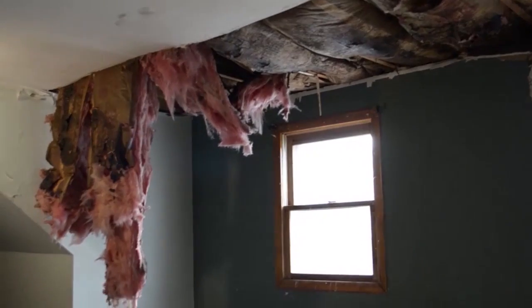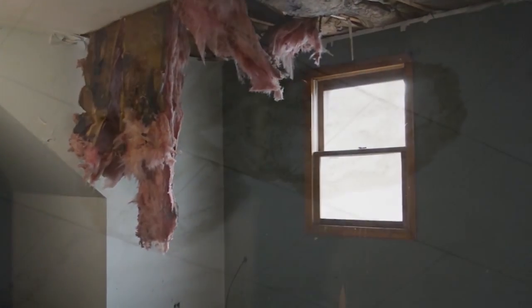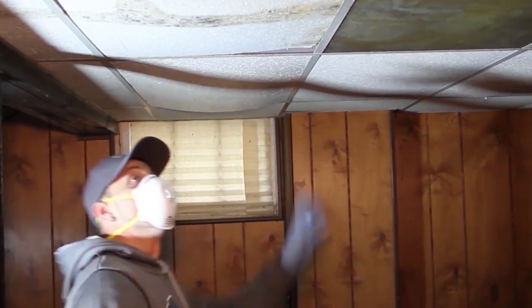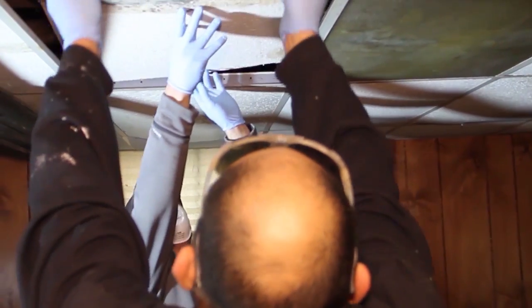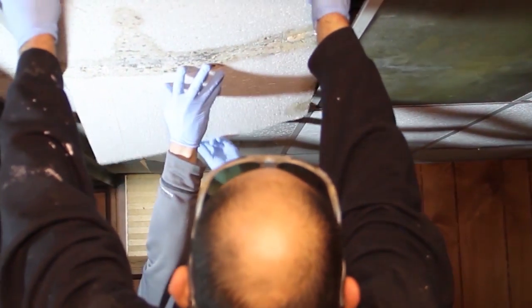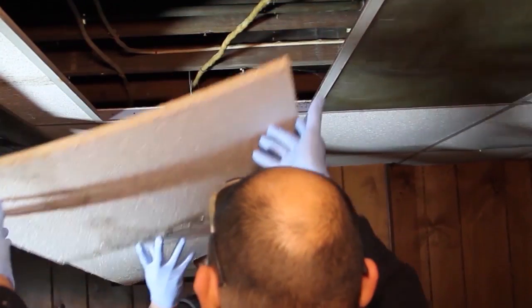After the mold areas are identified, you will define the surface type affected by the mold as absorbent or hard. An absorbent surface includes drywall, wood, cork, carpet, or ceiling tiles, while a hard surface would be cinder block, stone, concrete, tile, vinyl, or linoleum. If the water stain or mold is wet to the touch, check your work order to see if there's an allowable to remediate if a bid needs to be placed.